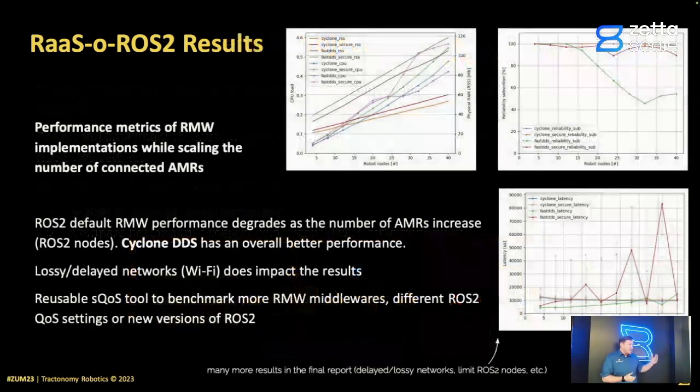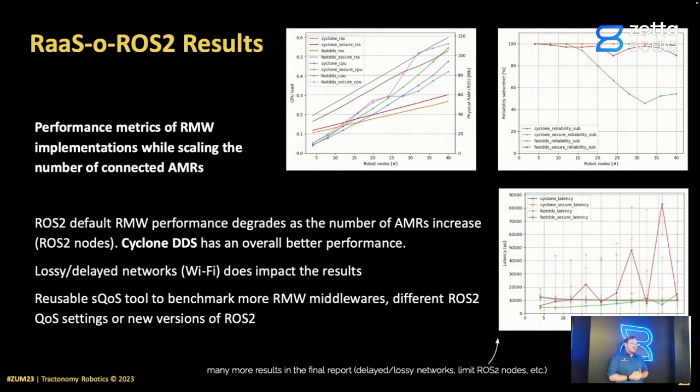Like a lot of presentations shown before me, in the beginning, ROS2 had issues with scaling. During this project, we tried scaling from one virtual robot to 200 robots, but we already got stuck at 40. At that time, every robot, in our case, had roughly 10 nodes. Currently, we have over 50 nodes for our single robot.